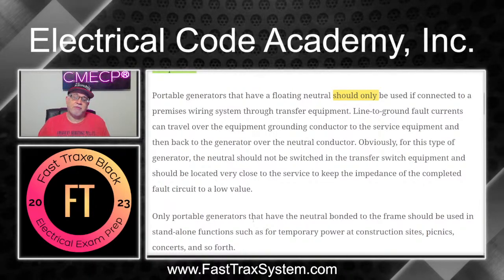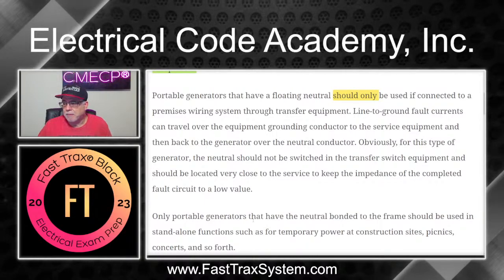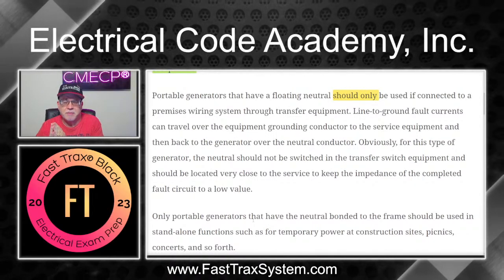And I would also say for homeowners, the people that want to buy just a portable generator to try to do backup power for their house, be very careful because a generator with a bonded neutral is a separately derived system, right?